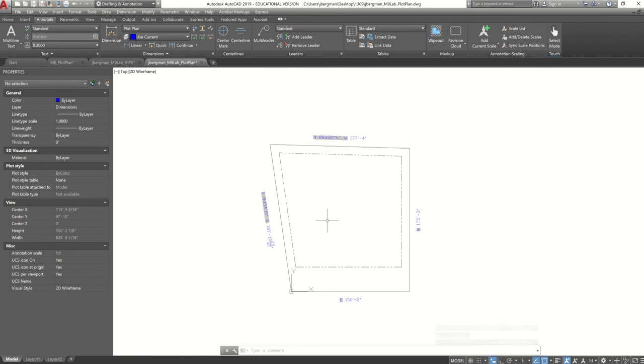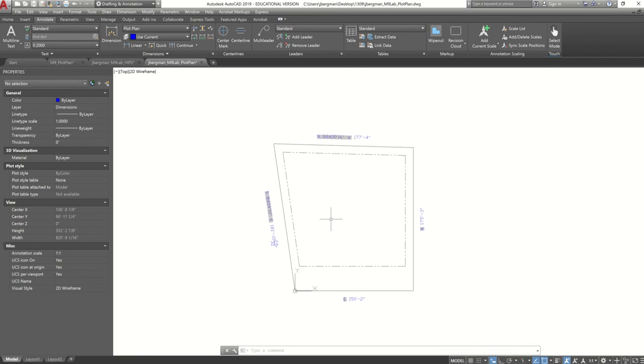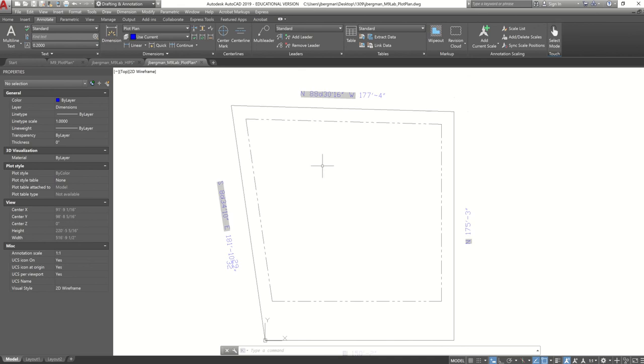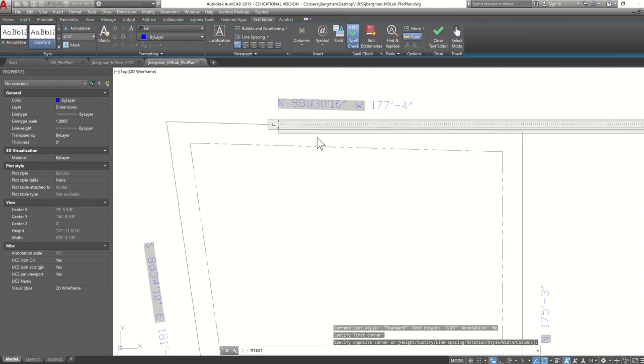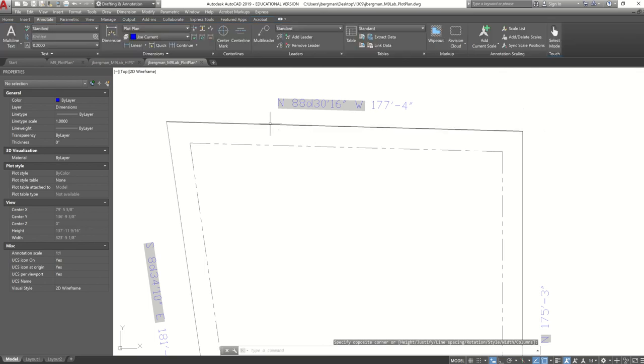Now I'm going to add in the annotations. So let's do this top one right here. We're going to use multi-line text, which is first corner. You're just drawing in that box there. And we're going to change this to 10-foot setback. Control Enter. And it looks like the dimension disappeared.